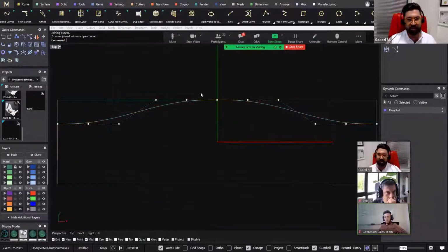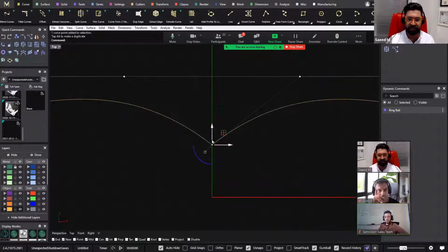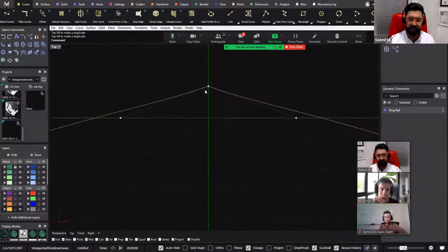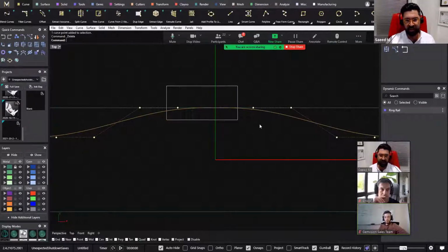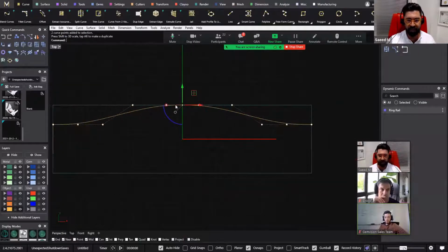I'm going to turn on the control points. You know, for each curve, the control points play a very important role. So when you join two curves, you will have a fracture, kink, or control point here. You can see when I move this point, the curve is going to be sharp. We have a sharpness here. So I'm going to delete this one. You can even scale 1D using the gumball to have a smoother curve here as you wish.